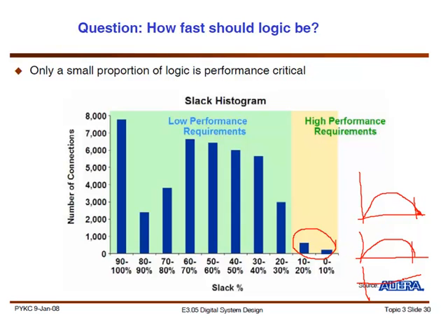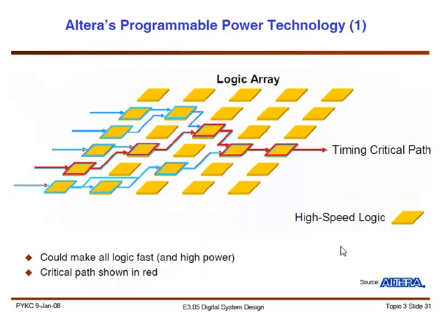And then your profile would look something like this. And this is called a timing wall. If you want to improve things, now you have a whole lot more paths that you need to optimize compared to the case here in which you only had a few gates that you needed to optimize. But these are some of the limitations of the FPGAs, that you can't get the most performance out of it. And that's one of the reasons that FPGAs are lagging behind ASIC in terms of performance.